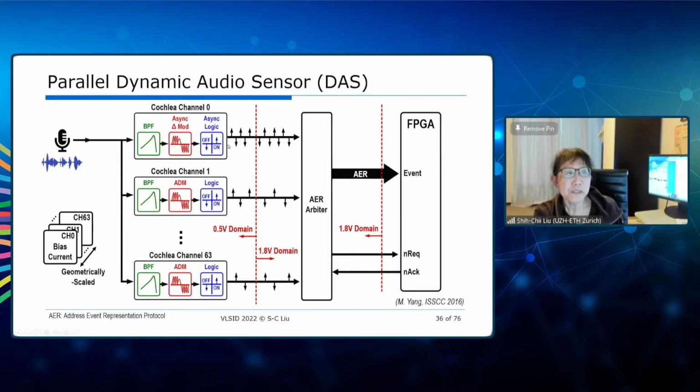In this case, we also have the on and off polarity spikes, which turn out to be useful when you want to do the reconstruction of the original input. Now, the on and off spikes are then transmitted off using the AER arbiter, and then you can, of course, connect now the AER output to another chip that talks AER, or also to an FPGA or to the computer.